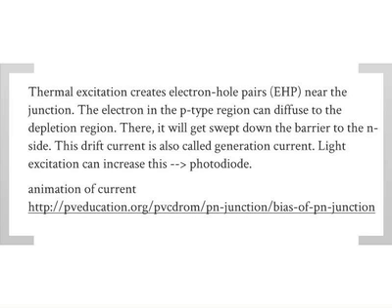Okay, so if you look at the band diagram, the p-type material, you have valence band, conduction band, or thermal. At any instant of time, some electron here can get bumped up there. This becomes an electron, this becomes a hole. This happens all the time, right? Because sometimes this kT over q can be close to the band gap. Remember, that's the definition of semiconductors. You get some of this thermal generation.